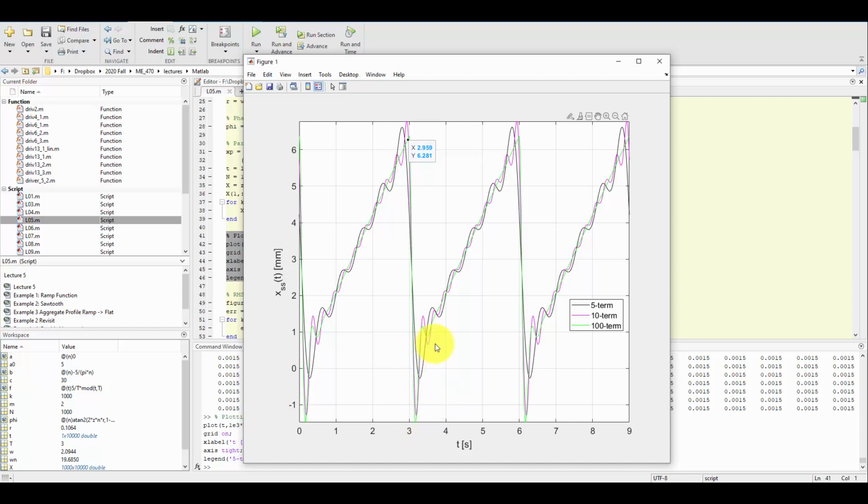So overall, we're seeing that this mass is basically following the same profile as the forces at steady state, which matches more or less what we've been seeing when we have forcing: once those transients die out, the output is going to match the input, maybe with a phase delay and with a different amplitude. And certainly we have a different amplitude because our output is in millimeters and our input was in newtons.